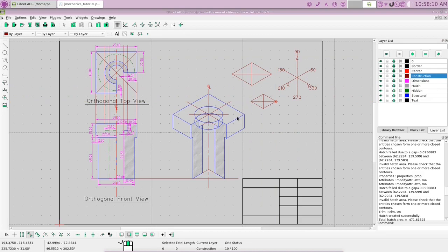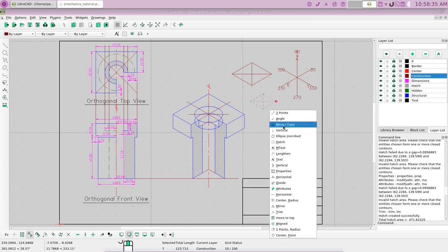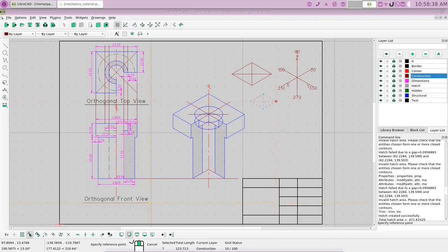Now, here is our 16 unit square, which will go on the center here and designate where our next circle will be. So let's highlight that, and let's choose move copy, and let's choose to snap on the intersection of this right there, and let's move this over to the end of our line here.